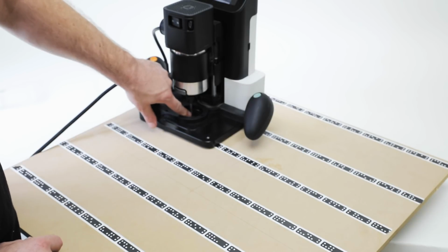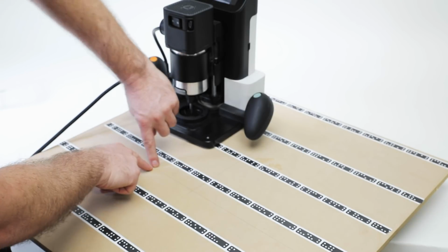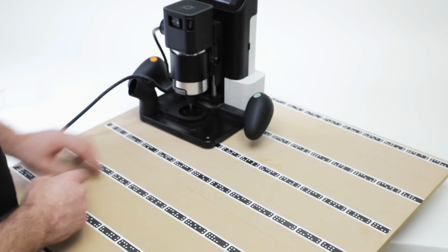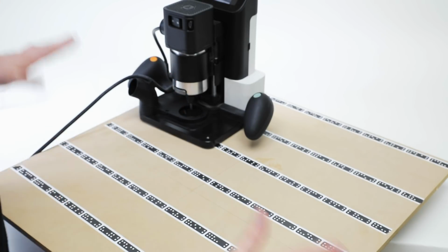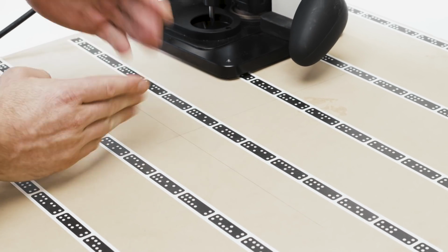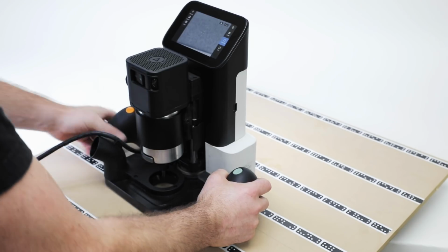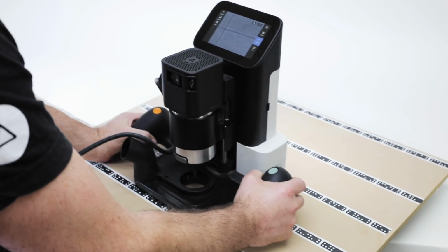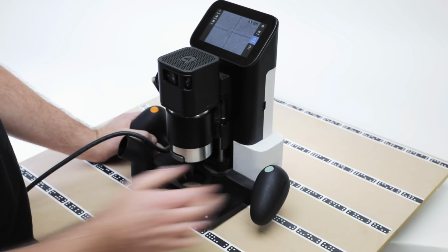So we're going to be looking at a cutter, an engraving cutter inserted the normal way up, so the point is facing down, and we're going to use that point to align to pencil marks on a panel. This doesn't make a lot of sense here, but if you're in the middle of a large floor and you've got a pencil mark that you want to align to, this gets us a really high level of accuracy. So I've scanned this in.